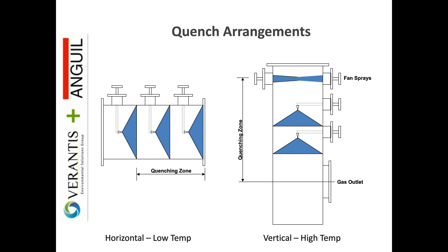A key with the quench design is we have to look at what's the inlet temperature, what's our safe outlet temperature, and then we have to make sure we have excellent mixing and we have adequate residence time. Another key consideration with a quench is we want to make sure that if we are recirculating anything to the quench and we recirculate any salt solution, we don't expose that to the very highest temperatures in that quench because we can over-evaporate and actually take that salt solution and make it into a submicron particulate that can come out your stack.